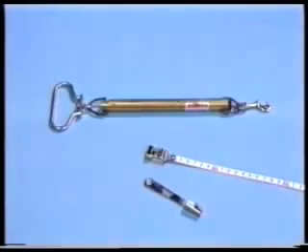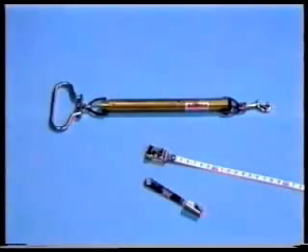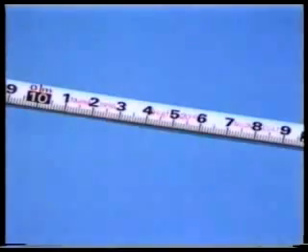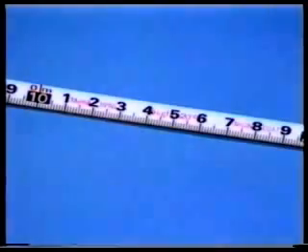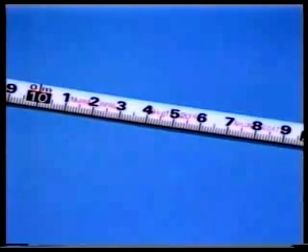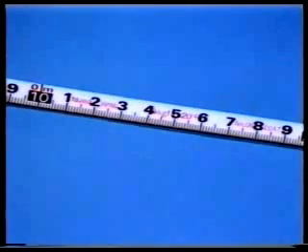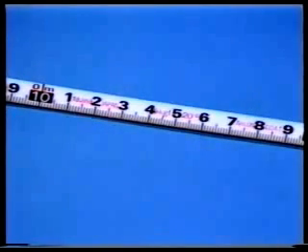The tension correction need only be considered when using steel tapes where high accuracy is required. The steel used to make steel tapes is elastic in nature, and if the tape is pulled, its length will change slightly depending on the amount of pull or tension applied to it. To allow for this, all steel tapes are manufactured and calibrated with a standard tension applied. For example, 5 kilograms force, which is about 50 newtons.